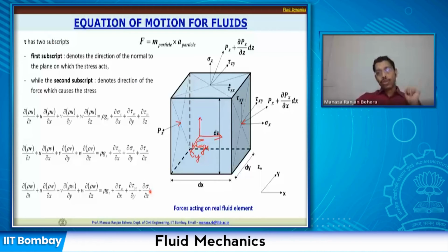So you have three more unknowns that are the normal stresses in all three different directions. So we have six unknowns now. Now look at this tau. So tau yx is equal to tau xy, so we will assume they are both the same. So let us say this is 1. Similarly we have tau zx, tau xz and tau zy, tau yz. So we have three more shear stresses.